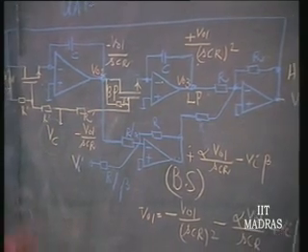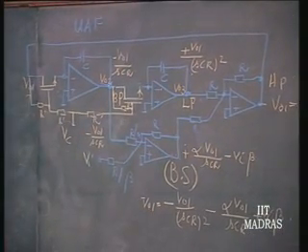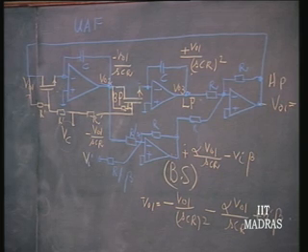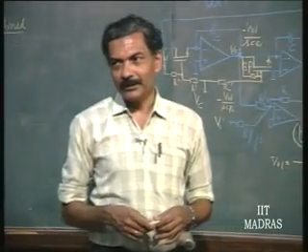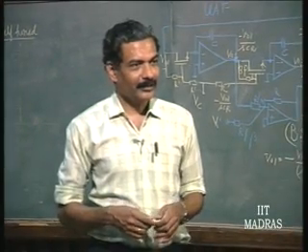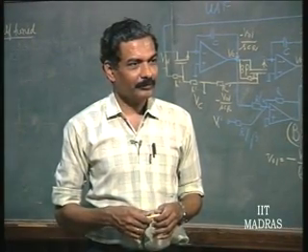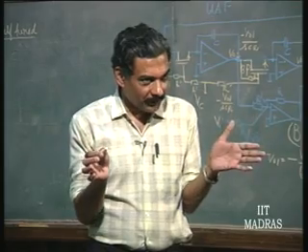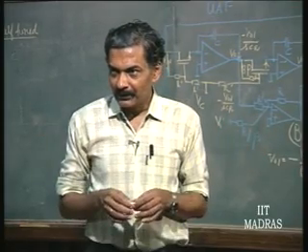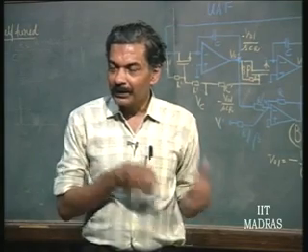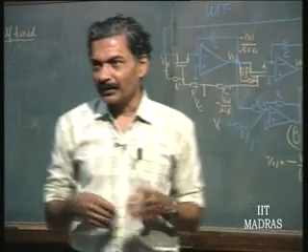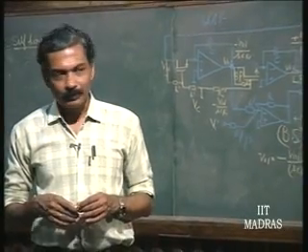not. Now, in this particular case, suppose you take the band pass output, how will you know that it is tuned? This is the same question, right, that I had asked the PGs last time. I am taking the band pass output for observation. So, how will you know that it is tuned to the incoming frequency, let us say 50 hertz or 100 hertz? How will you know?